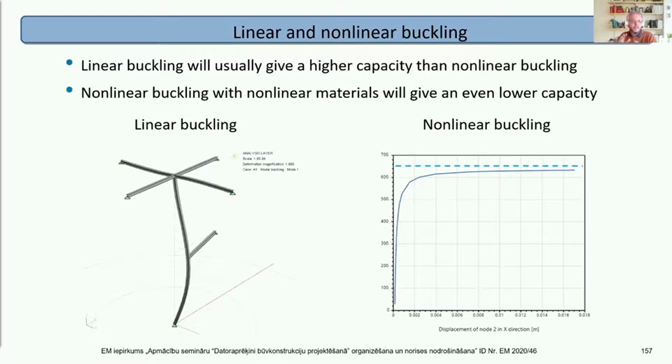So for a buckling load factor between 1 and 10, you need to do additional calculations, more investigation, non-linear buckling, and that sort of thing to find out exactly what's happening. Just because the buckling factor is 2 does not mean you've got a safety factor of 2. That is a misconception. It means it's getting close to failure, but it is affecting it.